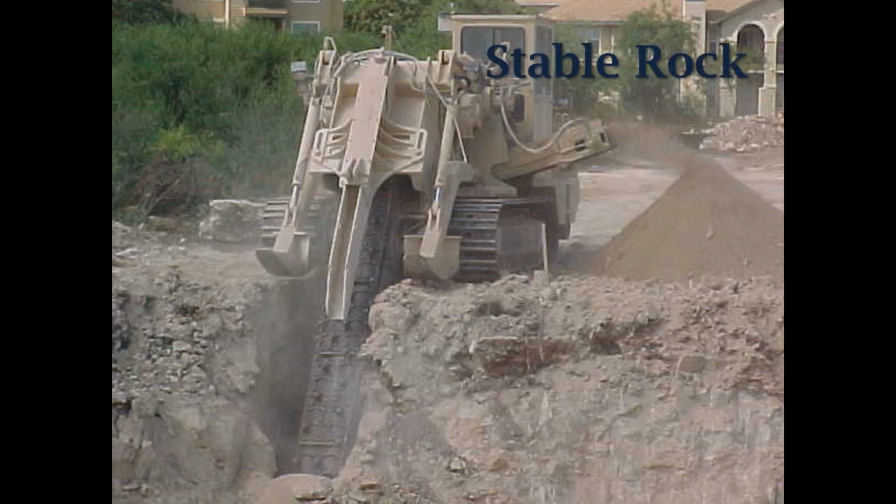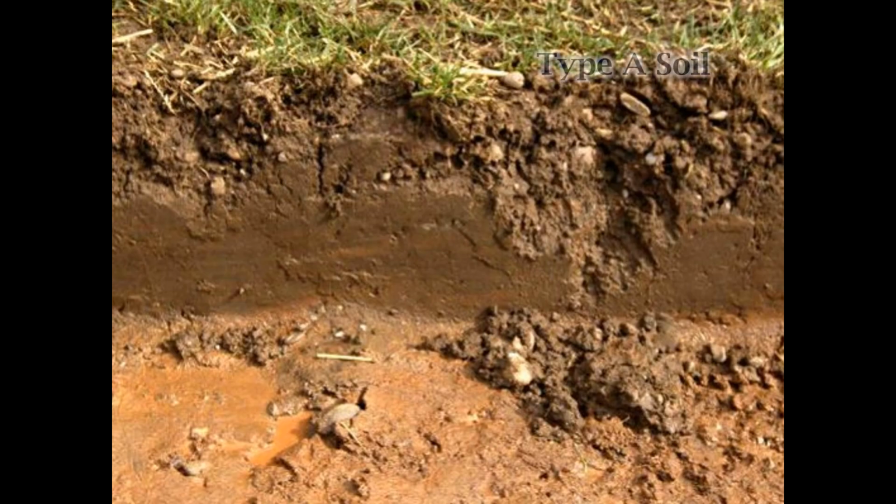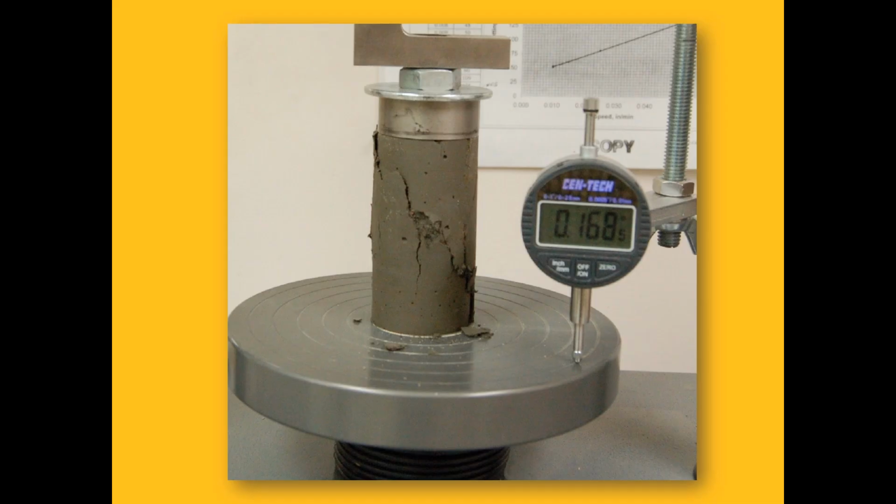Stable rock includes natural solid mineral material that can be excavated with vertical sides and will remain intact while exposed. Stable rock is usually identified by a rock name such as granite or sandstone. Type A soils are cohesive soils with an unconfined compressive strength of 1.5 tons per square foot or greater. The unconfined compressive strength is a measure of the shearing resistance of soils. The higher the unconfined compressive strength, the more stable it is.